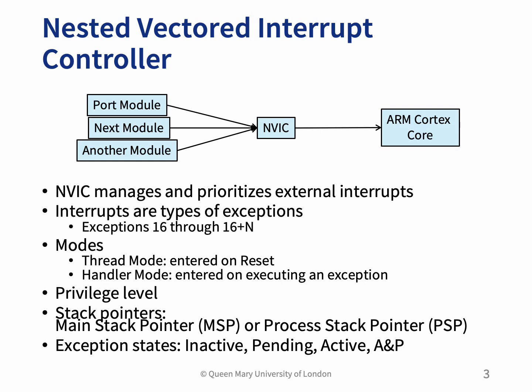So, this is done through the NVIC, or the Nested Vector Interrupt Controller. The Nested Vector Interrupt Controller is a method of prioritizing the interrupts. This is to improve the microcontroller's performance and, of course, to reduce the interrupt latency. In this figure, for example, you can see there are 3 modules, and then they are connected with the NVIC that forms part of the ARM Cortex core.